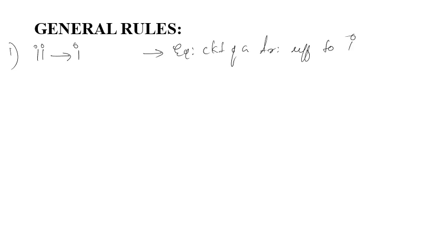That means here we are converting all the parameters from the secondary side to the primary side. So what are the main parameters? Nothing but resistance, reactance, and impedance. We can include these things in a single category. And the second one is currents, and the third one is voltages.